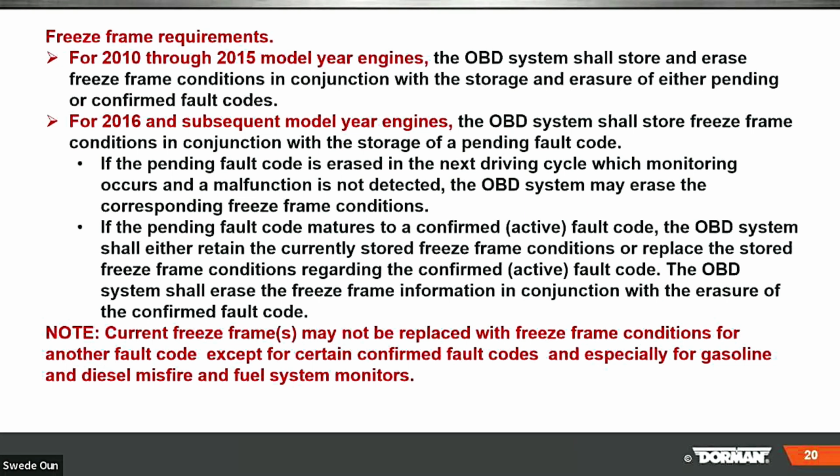For 2016 and subsequent model year engines, the OBD system shall store freeze frame in conjunction with the storage of a pending fault code. So again, you're going to have the handout, and if you choose to use it next time you work on something to figure out how you can get the information, go back to this. I'll be very honest with you, the lunch and learns are very fast paced.